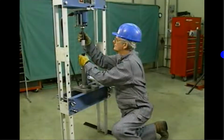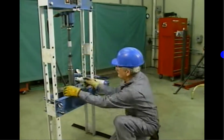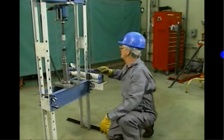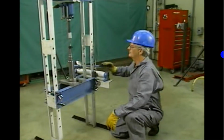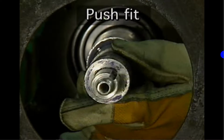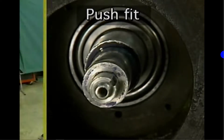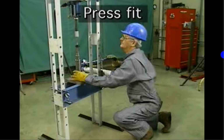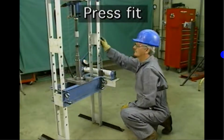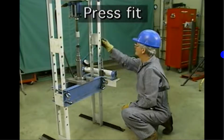The term fit refers to the tightness or looseness with which a bearing is installed onto a shaft. There are two kinds of fit: push fit and press fit. A push fit is a fairly loose fit. Usually, a ring that has a push fit can be pushed into place by hand. A press fit is much tighter. More effort is needed to press the ring into place. A press fit is also called an interference fit or a shrink fit.